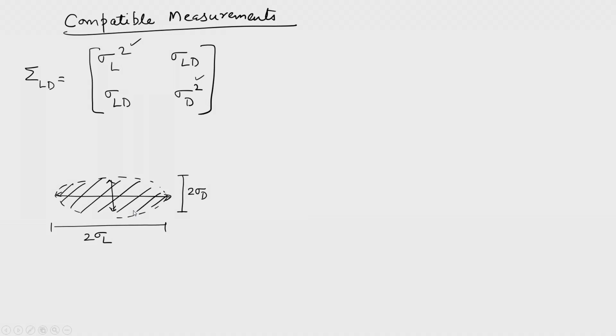Now what will happen, you see, I am wasting either a resource or I am trying to match two inappropriate resources. That means either I am doing length measurement so accurately that it is not compatible with the bearing measurement, or I am doing bearing measurement so accurately that it is not compatible with length measurement. Fundamental measurements are length and bearing, if you remember, in latitude departure calculation. So how can I do the proper selection of the bearing measurement instrument, that is the compass, and the length measurement instrument, that is the tape or total station? The idea is very simple here.